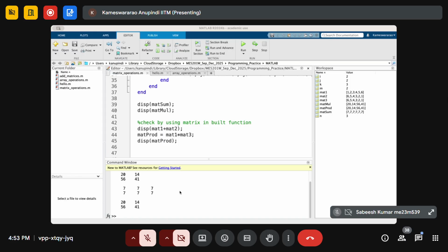Not only mechanical. Essentially what happens is that, let us say you take a finite element or even a finite volume in CFD, then your elements are only connected to the neighboring elements, right? So as a result, your dependency only comes from one cell to the neighboring cells, which could be left, right, top, bottom, something like that. It will not be connected directly to the other cells which are adjacent to the already existing cells. So you will not have any connection there. As a result, the coefficients will turn out to be 0. So for any cell, you will only see coefficients for the neighboring cells.